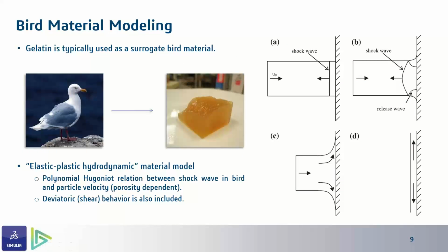Okay, so when we speak about bird strikes, it's extremely important that we also shed some light onto the shock waves. And the study of materials under shock waves means that it changes in configuration and in geometry from rod into a plate geometry. And these shock waves occur when a material is stressed far beyond its elastic limit by a pressure disturbance. So this pressure that is usually generated by the shock wave can exceed the material strength, the property of the material, by several orders of magnitude. And this is why we can view the material as a hydrodynamic material.